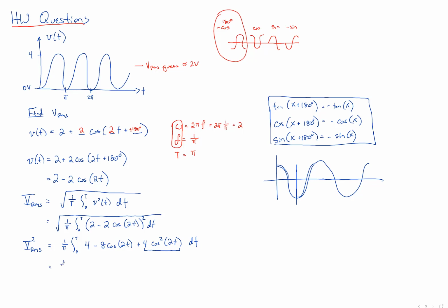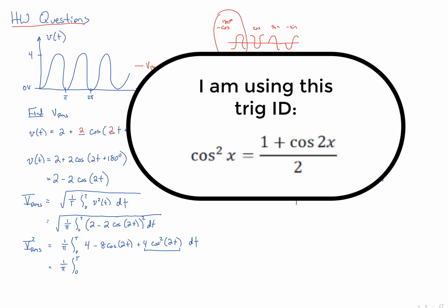I'll do one more step on this just so you see the whole thing. The DC term in this is a 2. So that 2 adds to the 4 and we get 6. And then the non-DC term is at double that frequency.